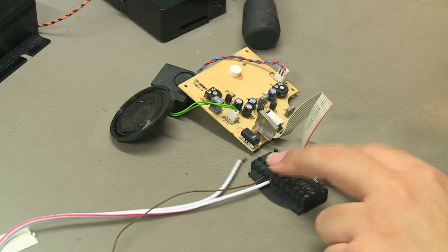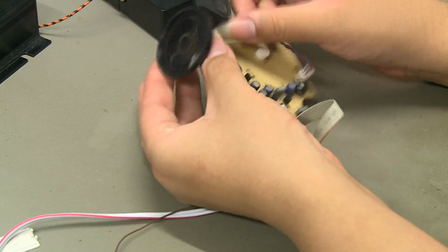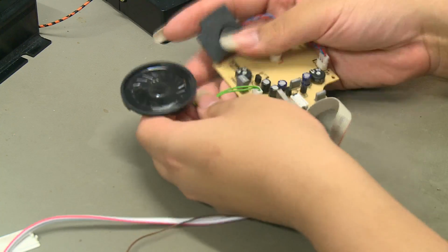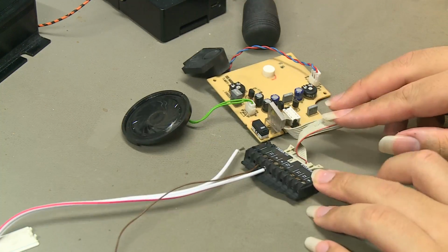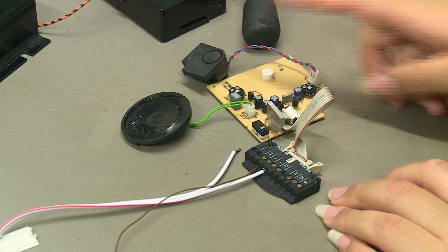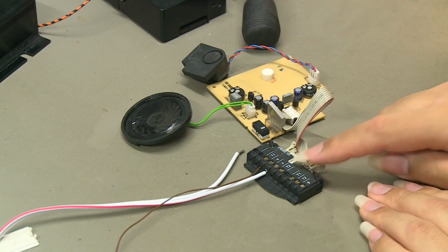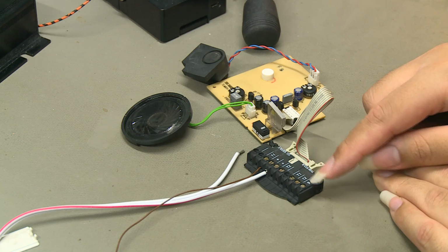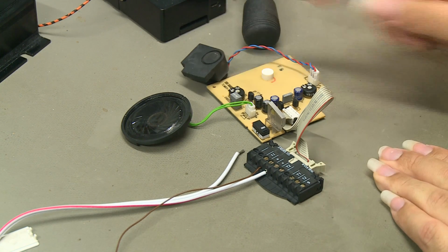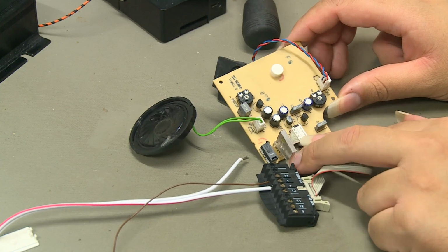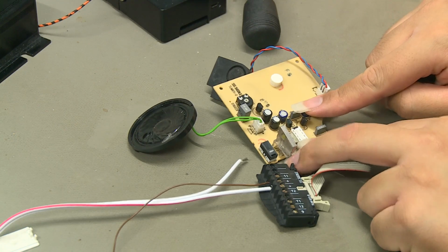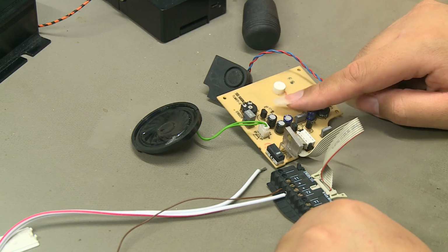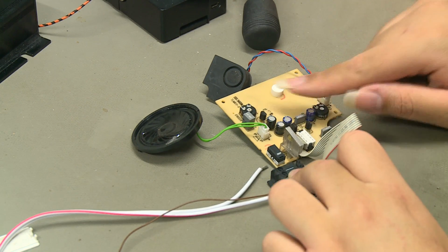Giving you a better view of everything. So here you can see this is the PCB with the loudspeaker and the microphone, and here you see the terminal block. So we found out that the loudspeaker is hooked up directly to the terminal block, at connectors 9 and 12 here, and that the microphone has this amplifier circuitry here. What this amplifier circuitry does is that it modulates the sound waves on the current that this amplifier circuit draws.